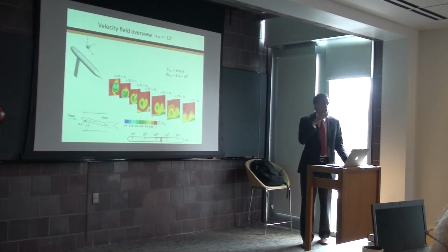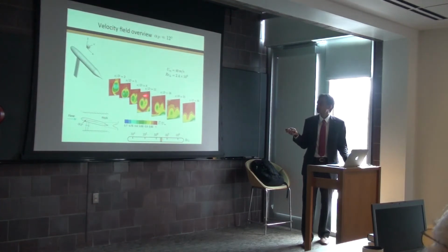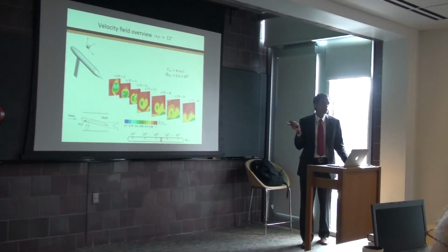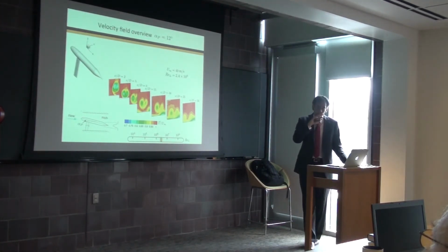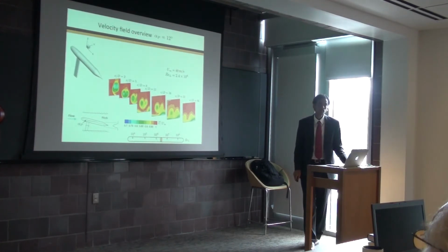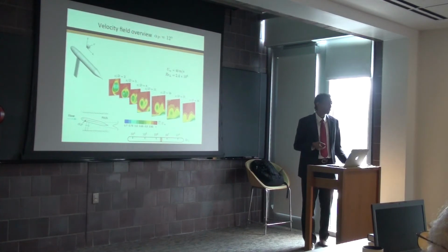What they do is sharp noses, high angles. So this asymmetry that we see is, as far as I know, not observed for blunt bodies at low angles. That's the claim. That's the difference, because you have vortex bursting at a high angle of attack. So that was an open question when we increased the Reynolds number, whether we might see vortex bursting or not.